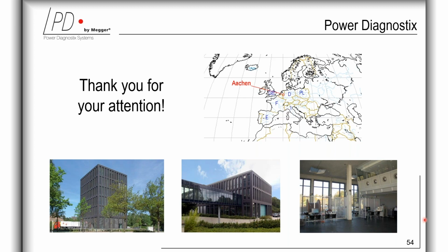So the PD measurement can furthermore be used for defect identification and also for location, as we do it on power transformers, to get a very clear idea of the root cause and the location of the partial discharge source.